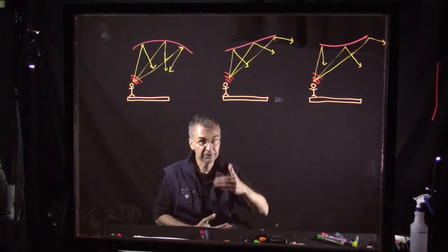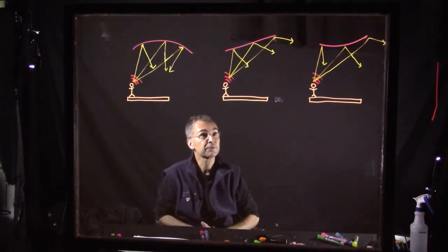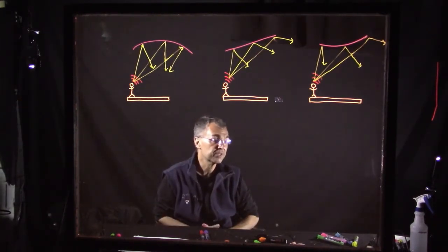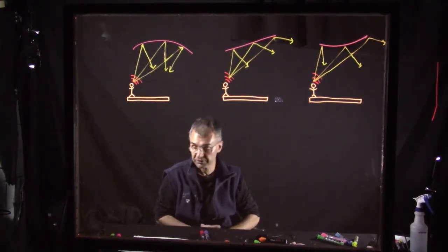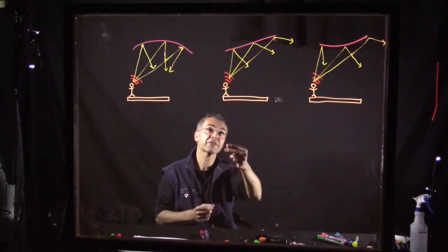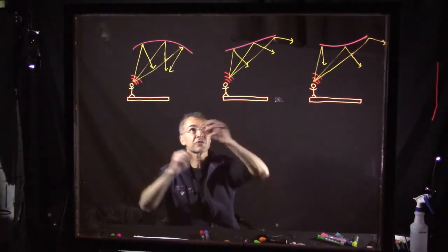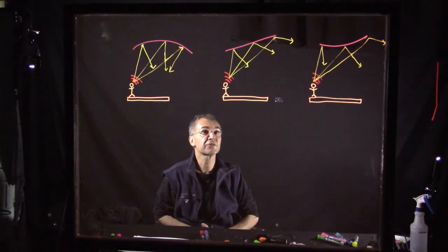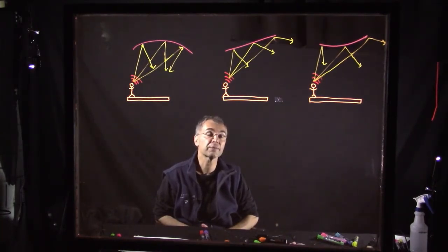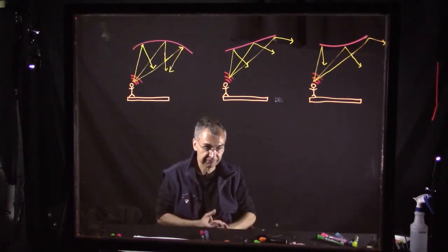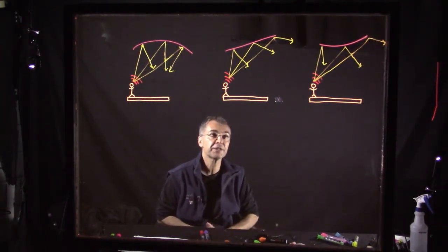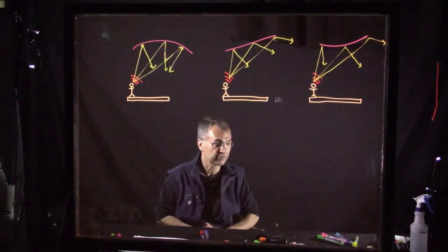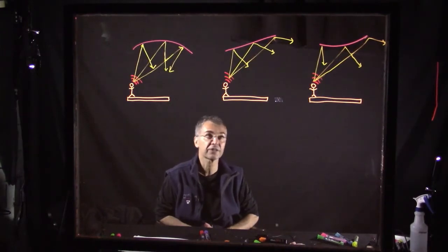And if the direct sound and the reflected sound all reach your ears within about 30 milliseconds, that's 30 one-thousandths of a second, which means that since sound travels at about 1,100 feet per second, about 1,000 feet per second, then you want the difference in path lengths between the direct sound and the sound reflecting from this side, from this side, and off that reflector up above the stage to differ by no more than about 30 feet or about 10 meters, so that your brain perceives it as just a full sound all arriving at the same time. If the differences are much larger than about 30 milliseconds, then it'll sound more like an echo to your brain, and that's a less pleasant experience.